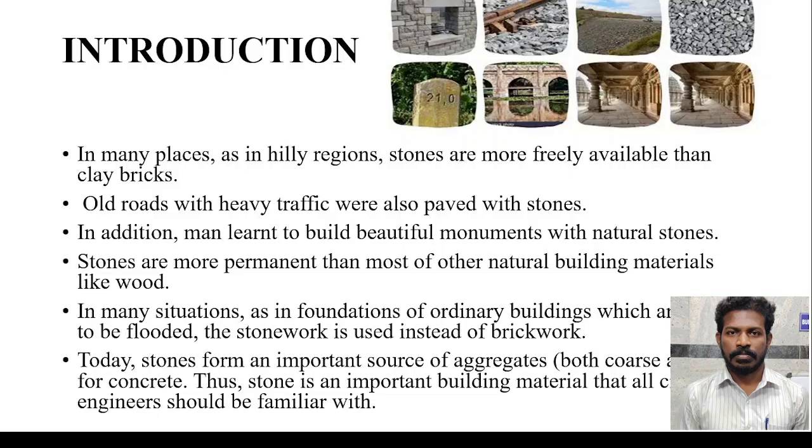In many situations, for foundations of ordinary buildings which are liable to flooding, stonework is used, because submerged bricks break down over time, but stonework remains stable. Today, stones are an important source of aggregates, which means coarse aggregate and fine aggregate. That's why as civil engineers, we should be familiar with stones.